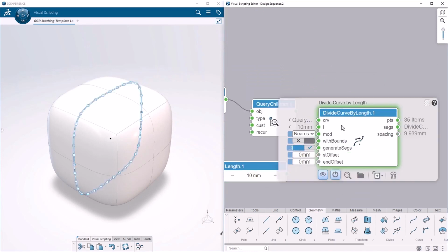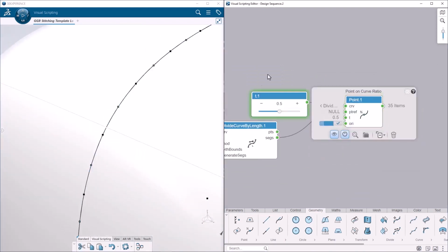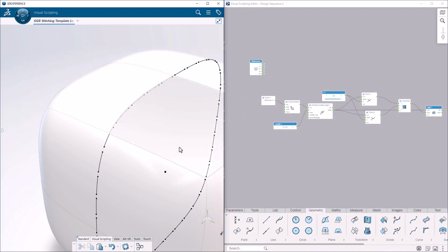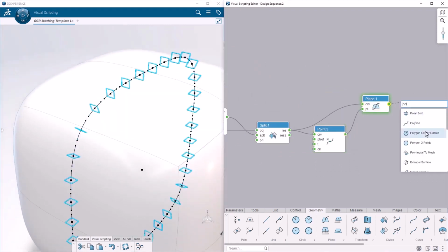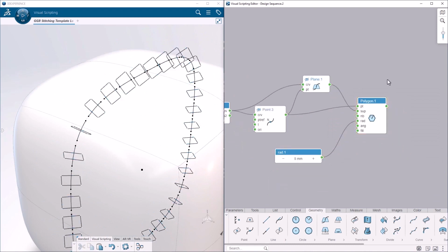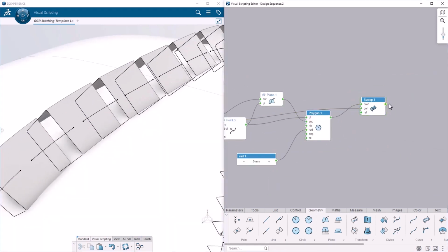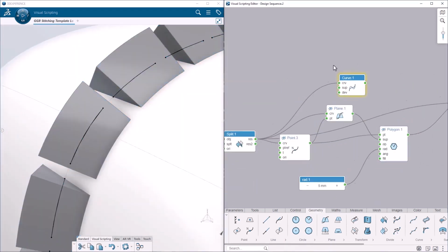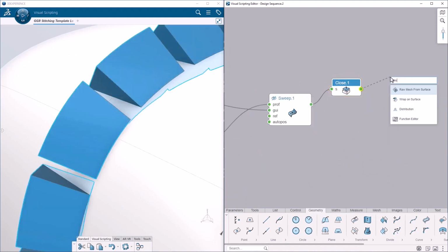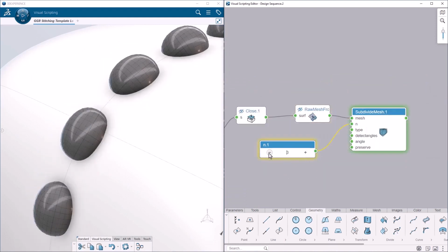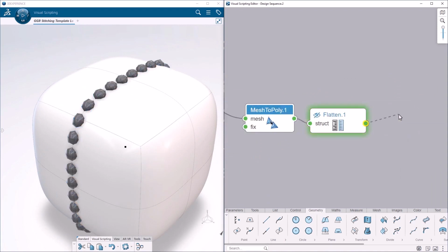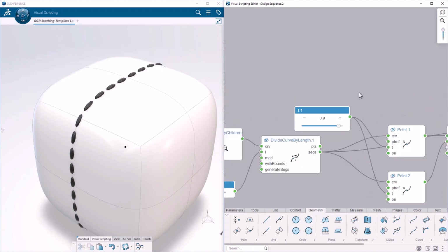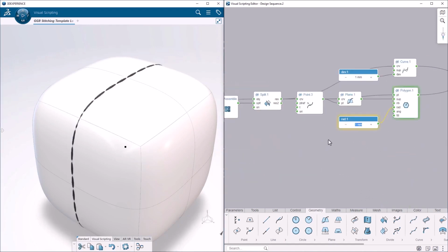In parallel, a third algorithm is created on a sample model, to automatically generate stitches from a simple curve. With basic geometrical operators, we are able to create prismatic shapes from points, planes and segments of the initial curve. We create a mesh from faces of the prismatic shapes, and we use mesh subdivision operation to smooth them. This simple technique is interesting to represent a first level of 3D stitches with a low cost of computation. Some parameters are defined for the length, the step and the diameter of the stitches.